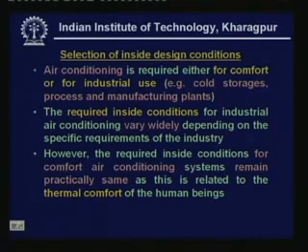Unlike industrial air conditioning systems, the required inside conditions for comfort air conditioning systems remain practically the same, as this is related to the thermal comfort of the human beings. In fact, the human bodies are very much alike. So the required conditions for providing thermal comfort to human beings remain the same irrespective of the location or type of the building or usage, etc. Okay, so we can formulate the required inside design conditions for comfort air conditioning systems. This is the topic of this lecture.